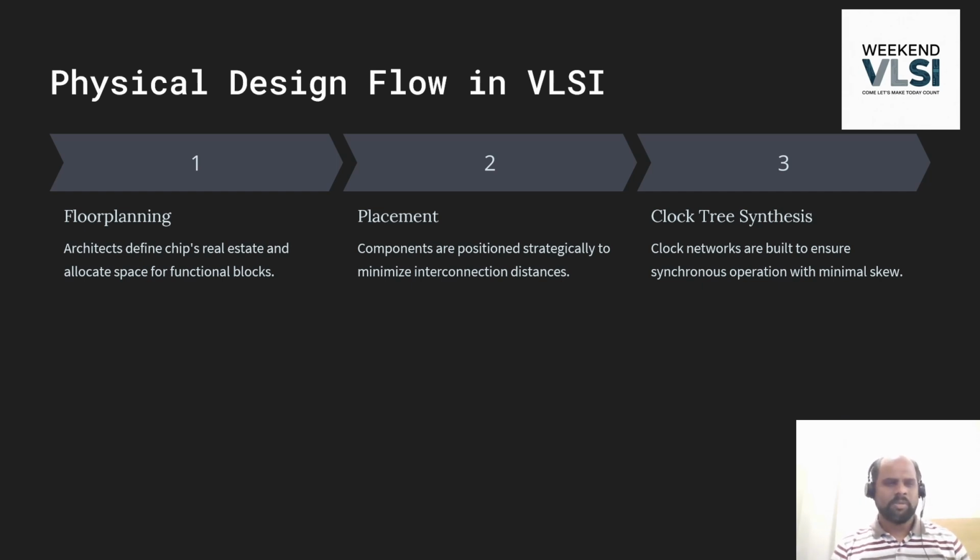Some examples of complex or advanced clock structuring are H tree structures. H tree is just a tree that will look like an H. Okay, the alphabet H. Why do we do it? We will get a better skew here. Okay, that's why the H tree is there. And multi-source CTS: nowadays, for high frequency circuits, multi-source CTS is very common. Instead of one single source, we have multiple sources so that the latency and the skew will be reduced. That is the target for MSCTS. And some more designs will have other kinds of clock structures like fishbone structures and stuff like that. Okay.